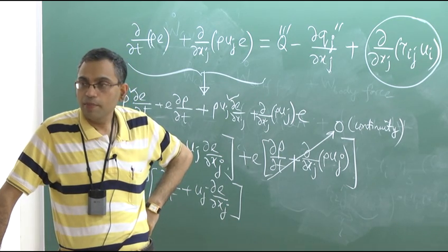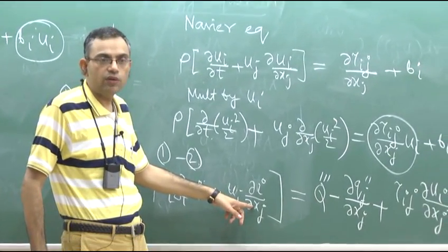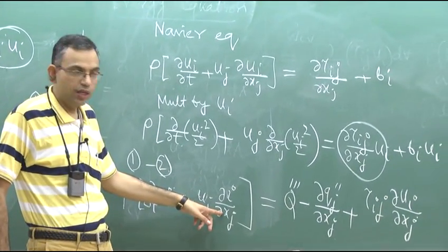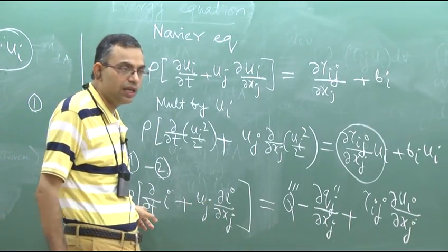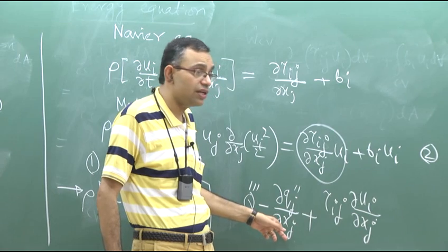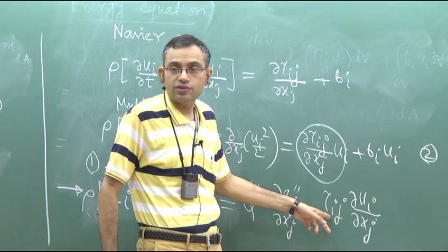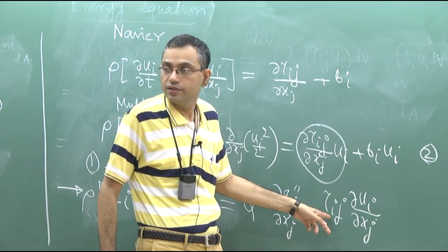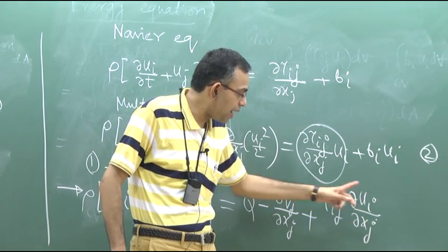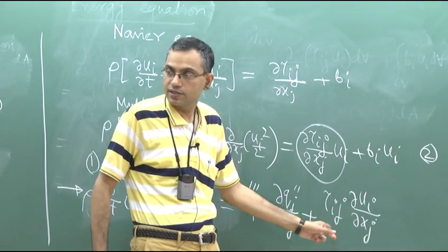So see, this is the total rate of change of internal energy. The rate of change of internal energy may be due to volumetric heat generation, surface heat transfer, but also due to stresses in the flow field. So this contribution comes directly from fluid mechanics.